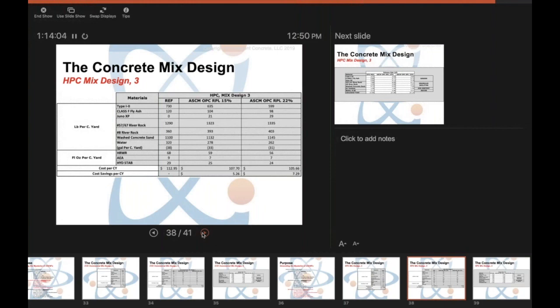And it's been awesome to see what we've been able to do with a whole variety of concrete mixes. And the time that I took today to show you these 3 different mixes doesn't even scratch the surface as to what you can do with Juno XP to save the world with all the concrete in it. And this mix design is self-consolidated concrete that we've used before, a 24 to 26 inch spread, a 26 to 28 inch spread, higher strength, 7,500 PSI plus or minus, still have that air entraining agent in there.